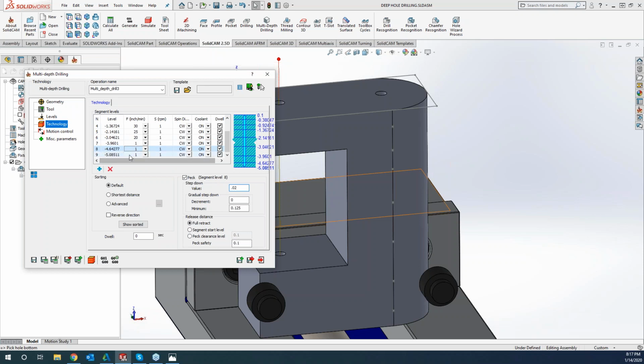So this is a great toolpath for any time that you need manual control over anything that's coming in on a center point. What Kevin's showing you now is applying the drilling. However, this can be applied to rotary broaching that comes in on a center point, where you want to approach and feed in slowly until that broach engages the material, and then you can pick up the feed rate.